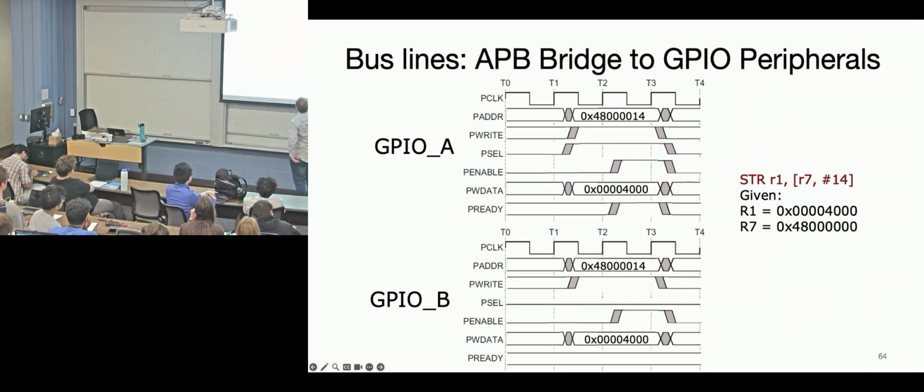So some people are like, does it have to be like this? Like, I want it to be a different way. Great, write your own port or write your own bus, right? There's lots of ways it could be done. Just telling you how this one is done. So there's a setup phase and then an action phase, and p-enable is saying, okay, all this data is ready. So it's a minimum 1 clock cycle. It could be multiple clock cycles. I don't know why the initiator could take multiple cycles.